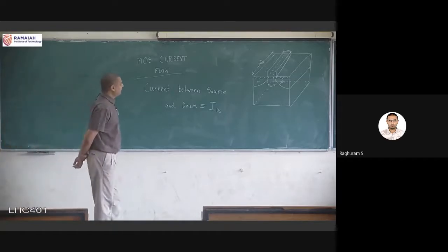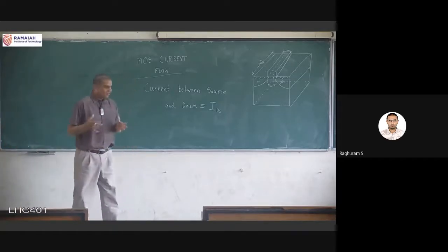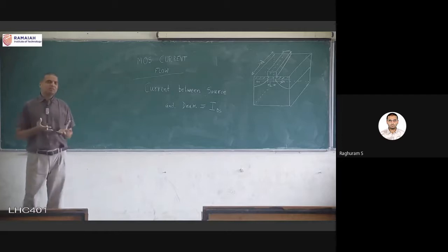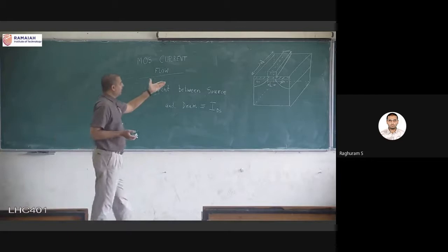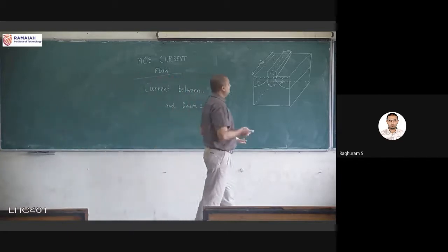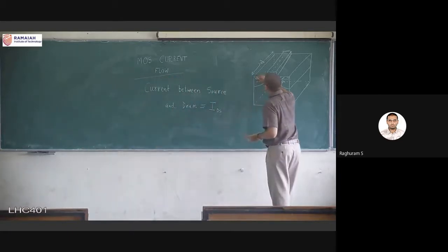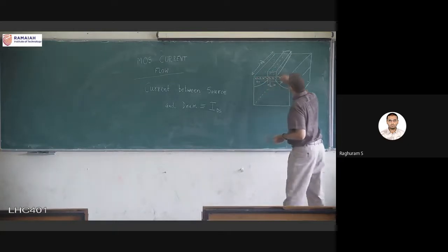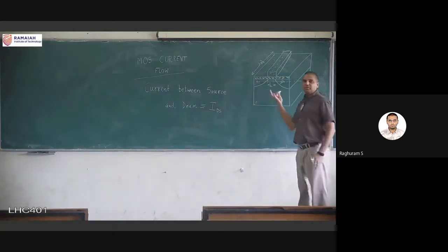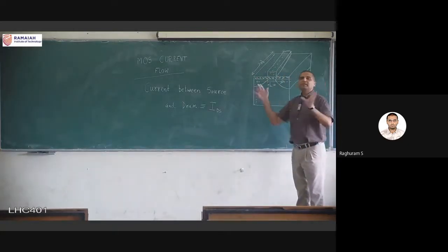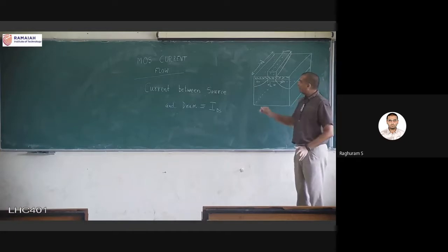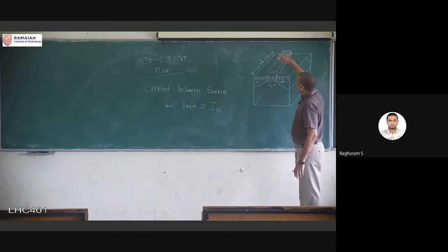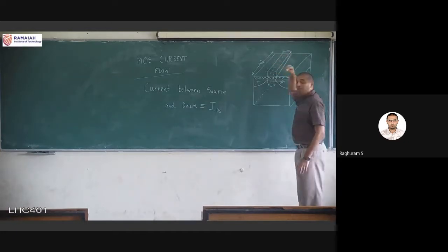It's very simple, right? Because the functionality, the way this whole transistor is designed, is that the gate terminal should not participate in current conduction. It should be isolated from the rest of the transistor. If it is completely isolated, then what is the point? There's no point in gate at all. So it is not completely isolated. I can put a voltage in the gate terminal, and there will be an electric field.